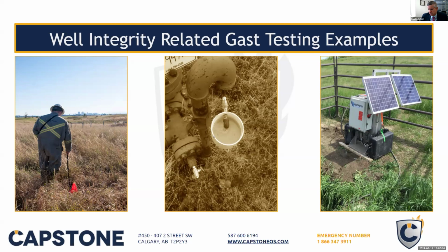In the middle, you'll see what's known as the infamous Canadian bubble test. The regulator here has a standard test. We have to test casing strings for flow with a 10-minute test in 1 inch of water, and you can have no flow for 10 minutes.